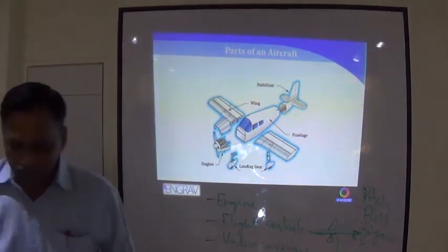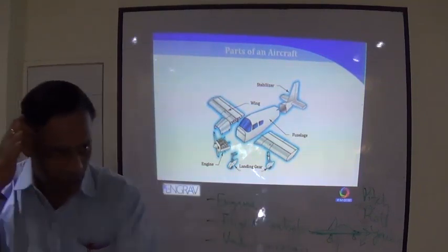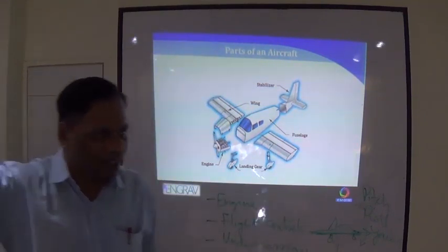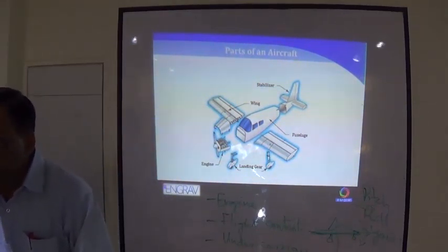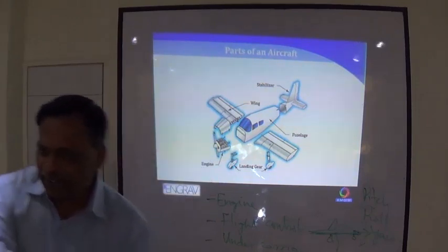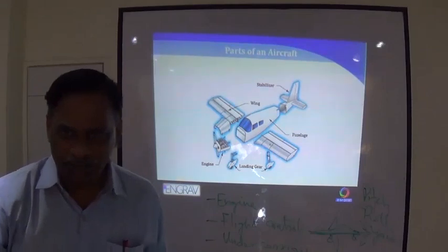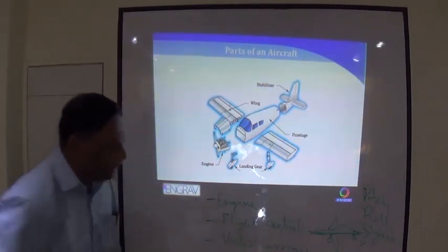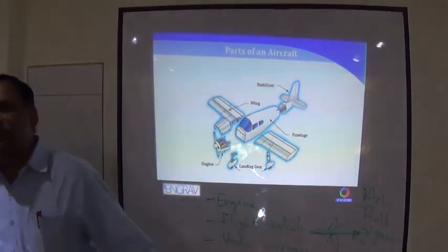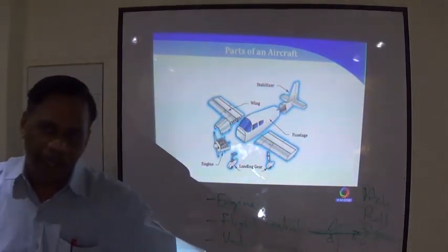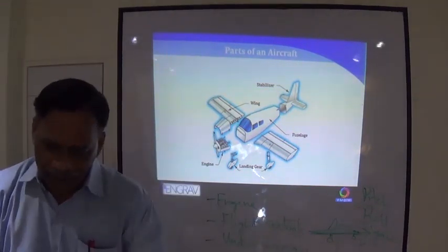If you try to do zoom left like this, then the aircraft will skid. That's what happens. Most of the youngsters I see falling down, it is because of this. They're going at high speed, zoom, they come and they skid. What you should be doing is a coordinated left turn. Then you would not fall down. So in flying, you want to take a left turn. You first do a slight bank. It's called banking the aircraft. You put the left wing down, so you do this thing.